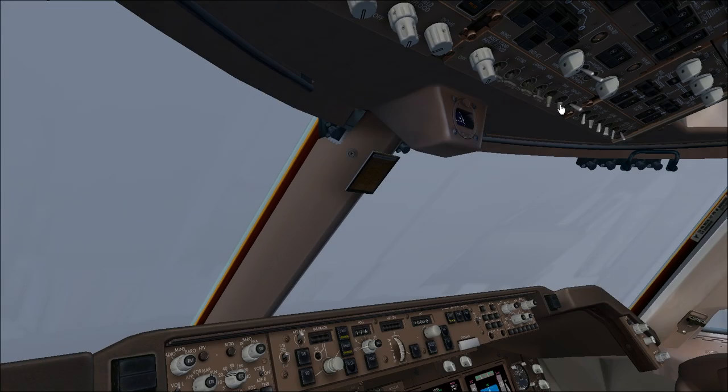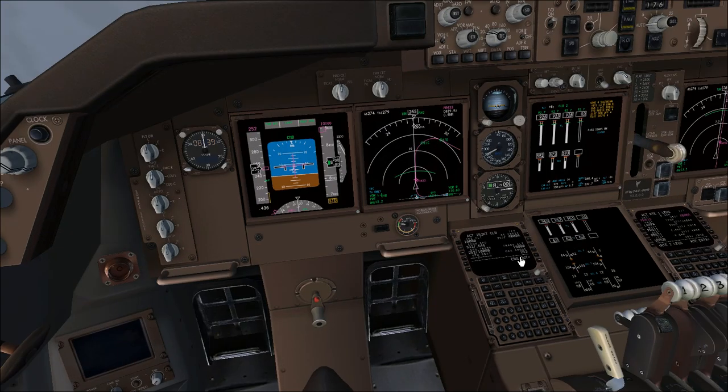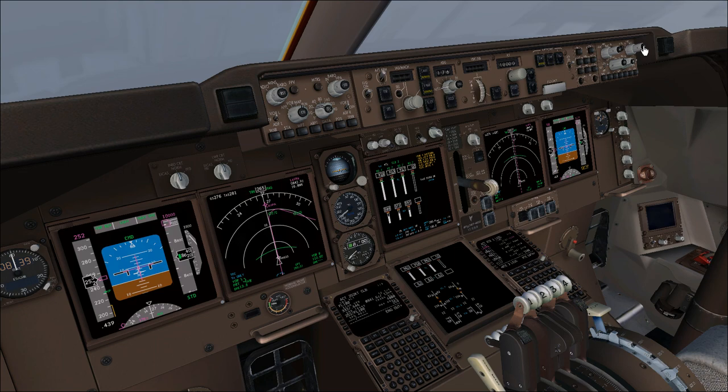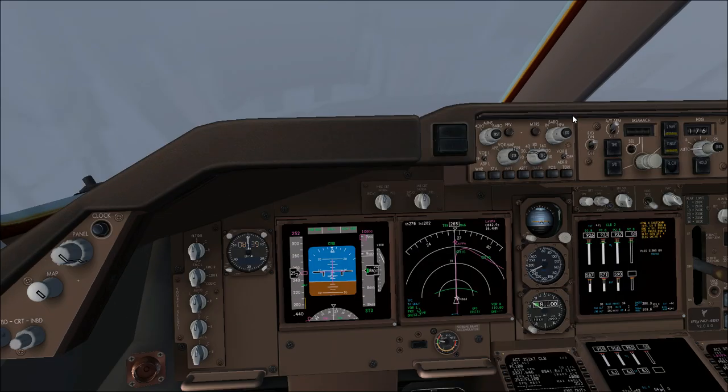We can deselect the lights. Wing off. And the next one is actually selecting standard. I got this wrong because I said transition altitude to 18,000 feet. The transition altitude in Porto is 4,000, so we can set 4,000 standard on both sides of the aircraft. So you can see now we are standard. Anyway, the QNH was 1013, so we don't have a big error.